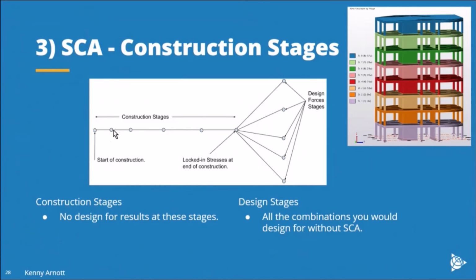Another point here is that during the construction stages, although we determine forces in all of these construction stages, we don't actually do any design for the models at each of these levels because the loading isn't taken to ultimate limit state level in all of these. We're kind of working with a working load level during construction, so it's very unlikely to be critical, and we don't complicate the design with that. And at the design stages, as I said earlier, that's where all the combinations that you would normally have considered in the design get dealt with in the stage construction analysis.